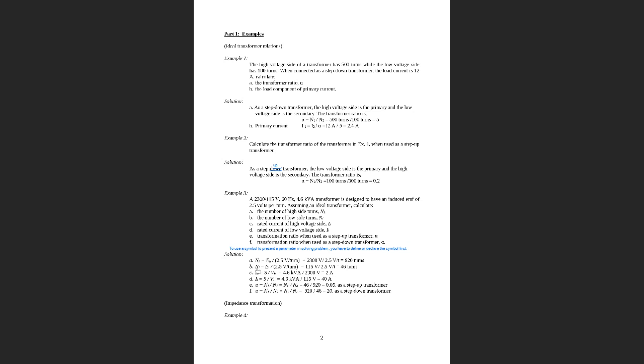And similarly, we can find the turn numbers required for the lower side, which is the voltage required for the lower side over the design per-turn voltage, which is defined here as 46. And for the transformer, the total rating power is 4.6 kVA. This total power over the high voltage side rating voltage gives the high voltage side rating current, or design current, which is 2 amperes.